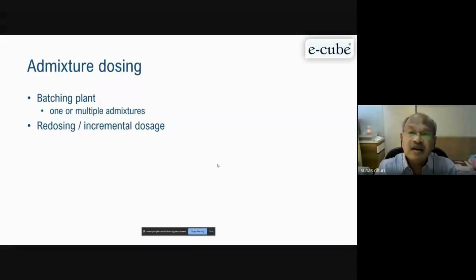If you add it along with water, because most of the batching plants are designed by mechanical engineers and they don't know the concrete. If they sit with the concrete technology and then design a batching plant, it will give better performance. Now, suppose there are 180 liters of water and 10 liters of admixture, I'll mix it. The basic concept is it should be distributed everywhere.